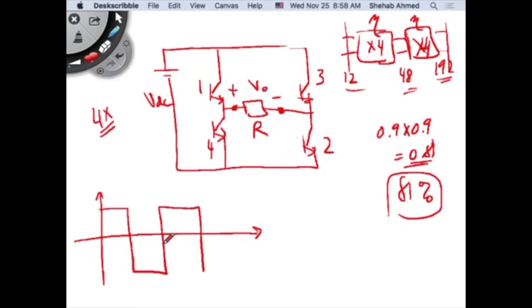In your case, in the full bridge DC to DC converter that has a front end, basically, which is a high frequency DC to AC inverter, you don't care about the frequency content. But if you do the Fourier series for this, what will you find? You will find a lot of harmonic content, because it's a square wave.